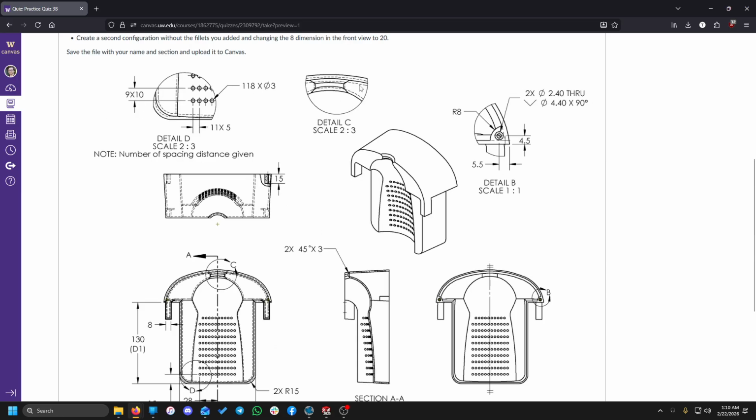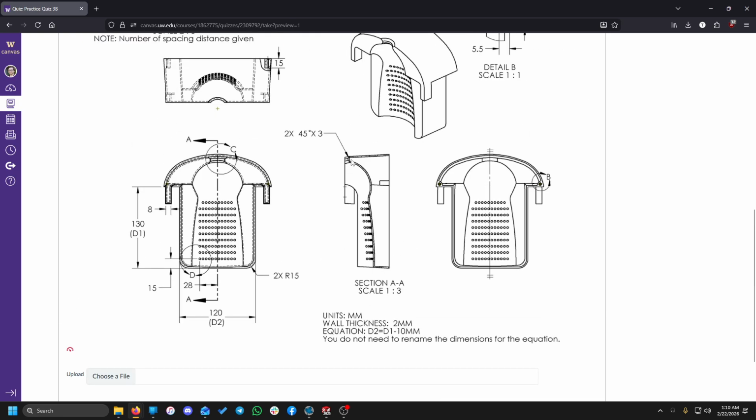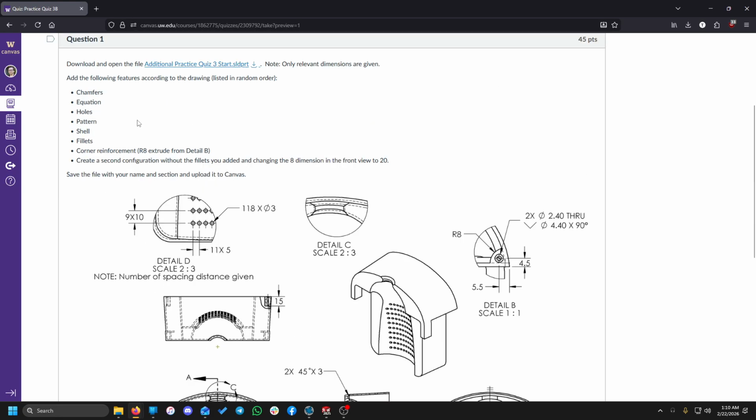So these ones, taking a look at our top view, it sort of seems like we don't have the chamfer sort of propagating to the inside of our object. We would expect a lot more hidden lines going on there. It's a little harder to spot down in our section view, but we do also see that we don't have sort of the matching diagonal lines on the inside. We would also then see a bunch more edges in the top up here. So the chamfer is going to need to happen after the shell.